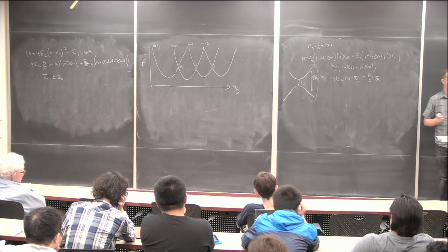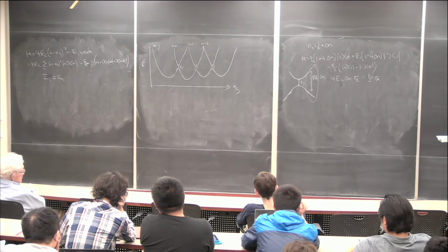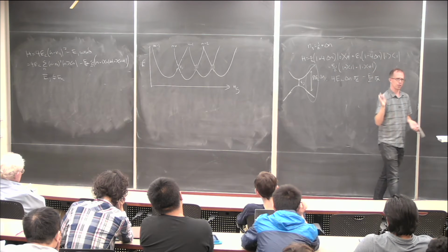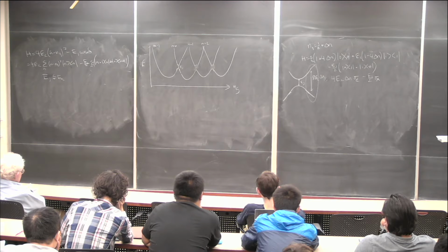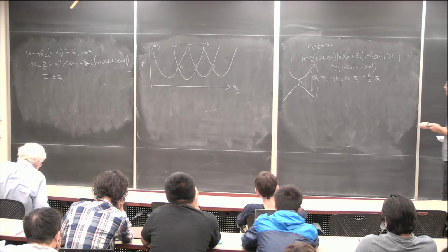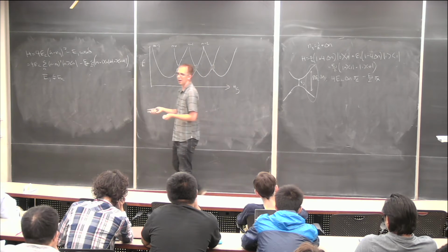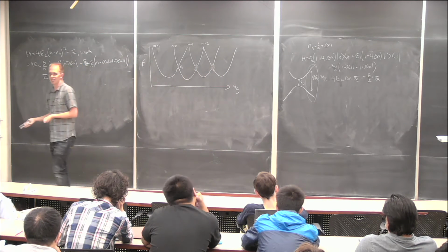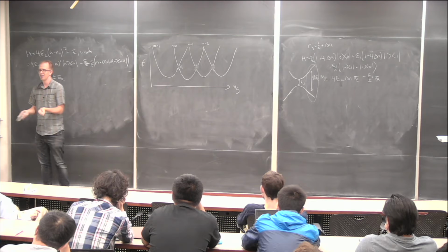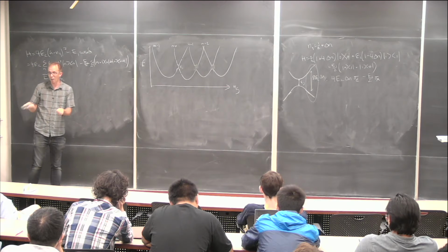But there's a problem, and it comes from this first thing I said. In the early days, it was so good because you could tune this thing, right? You really wanted a 5 gigahertz transition. You just picked EC. You designed a circuit so that EC was close, and then you picked delta n so that this energy difference was 5 gigahertz, or exactly the frequency you wanted it to be. Tunability is a double-edged sword, because if you can come along and use a gate voltage to apply some particular bias voltage, then the universe, the nasty things that exist on chips when you look at them under a microscope, can also come along and twiddle voltages in ways that you don't control.